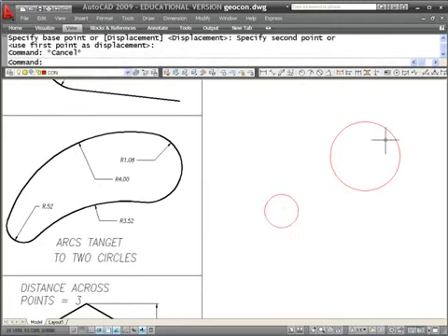Okay, now what I'm going to do is connect that large circle and that small circle with a convex arc that goes on the outside and a concave arc that goes on the inside. Again, in AutoCAD, circle TTR and the fillet command could easily accomplish that, but we're going to use traditional techniques so that you understand how they work. Let's start with the concave arc in the bottom. What we're trying to locate in every one of these cases is the center of an arc that will be tangent to both of those two.